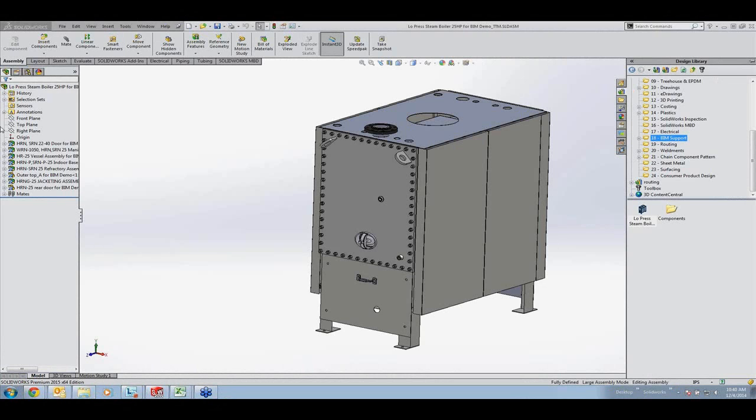Now what we need to do here is we need a T, or a cross, actually, to split it into 3 different directions. Create some little stubs here on the end that can then be attached to my endpoints here. Now, the endpoints here are smaller than my current HVAC, so I need to add a reducer here. The reducer will automatically size itself based on what I'm attaching it to.